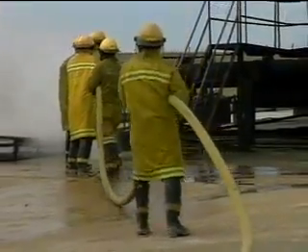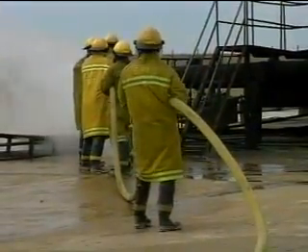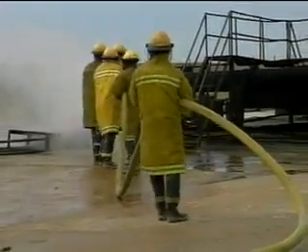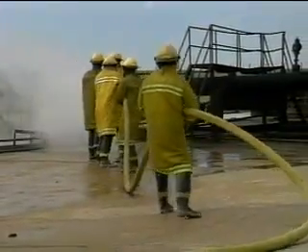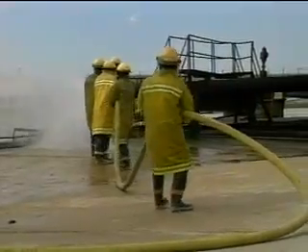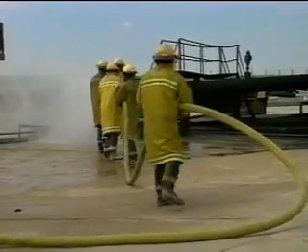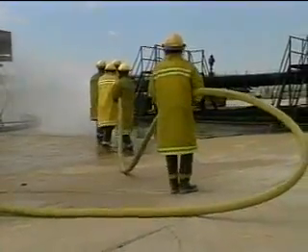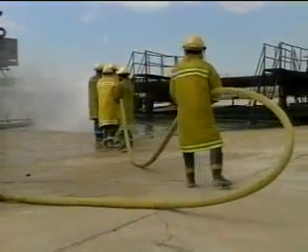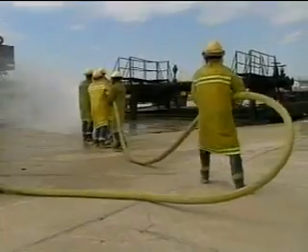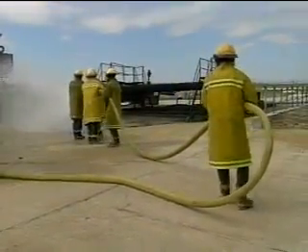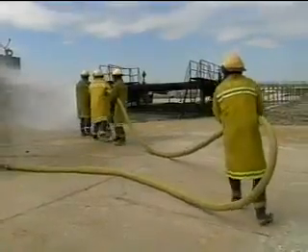When the nozzleman shouts, "Prepare to back out," the last man shouts to the person in front of him and says, "I'm dropping back," and drops back, picks up the hose, allowing it to drag on the deck between him and the other team members. The last person pulling the hose must make sure the hose winds in an S pattern, not in a loop. This ensures that the hose doesn't kink should the team need to move forward again.